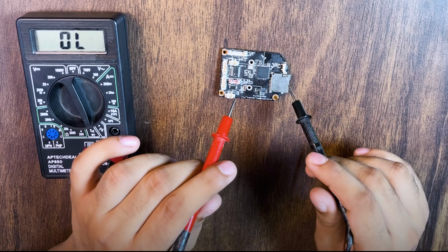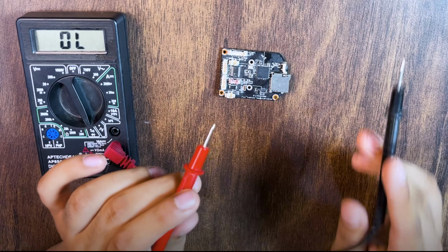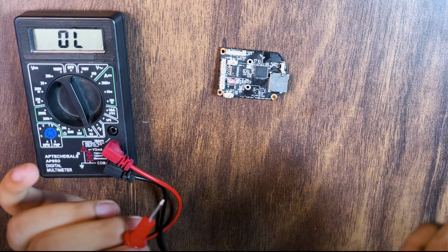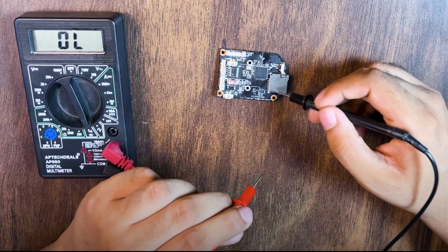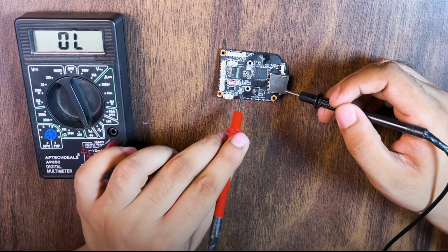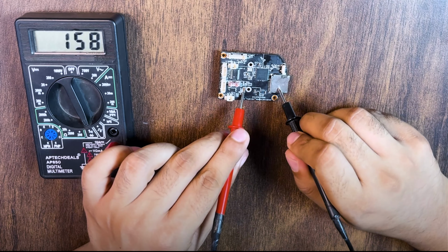Usually, the shield around a SD card reader or a USB port or your power adapter, etc., is actual ground. So you could use those as a reference, and that's what we're going to do right now. We have the shield of the SD card over here, which we'll use as a ground reference. So one probe on the UART ground port, other probe on the shield,